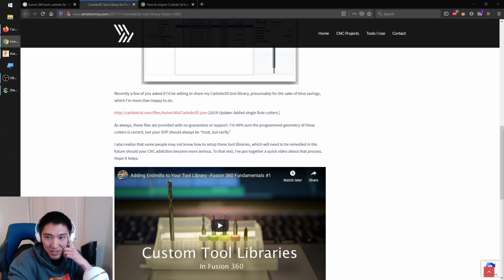I've been using double-sided tape for my projects. Are there cases where you're aware where double-sided tape is best avoided for cutting wood materials? The only time where I would highly recommend against using double-sided tape is if you have a cupped or warped board, because then you don't get good surface contact between the board and your waste board. And if you can feel a little rocking in the board, it's not going to be held securely. In those cases, you'll want to hold it down from the sides or from top clamps.